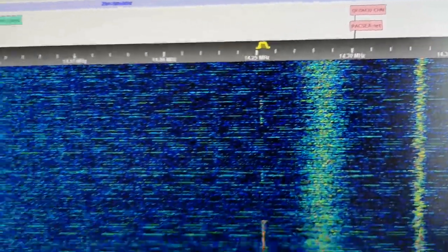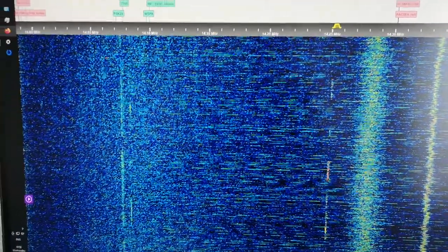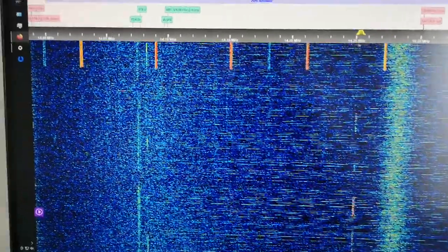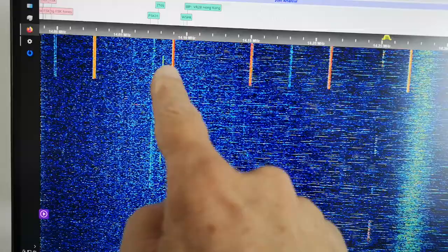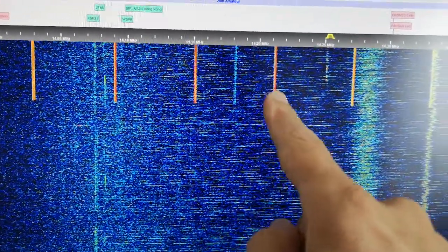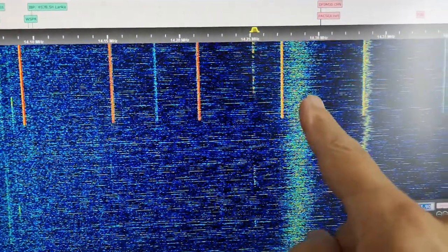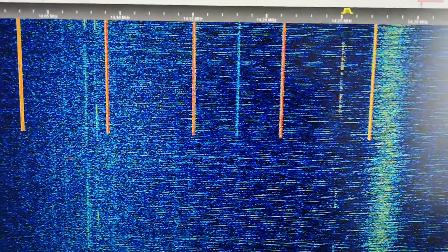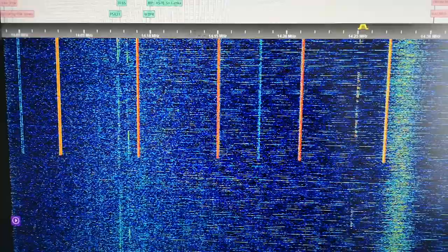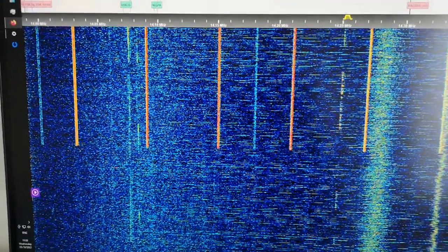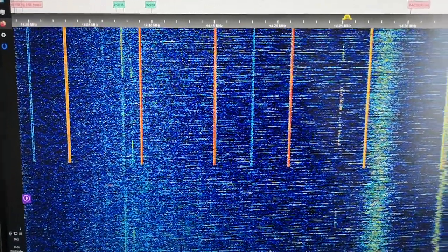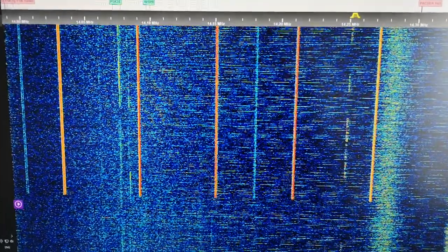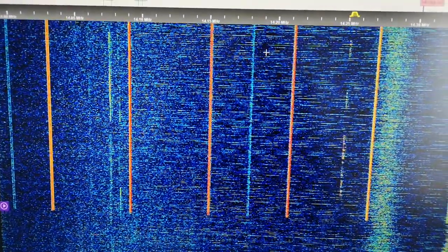It's now switched to 100, so the display's paused, but now it's reconnected at 100 megabits, and you can see here these red spurious signals. I don't want them there. They're about 30 kilohertz apart, regularly spaced over the whole radio spectrum, practically from 0 to 30 megahertz. They were causing a real problem. I could barely receive any other signals. And the simple way to make those go away was to change the speed of the Ethernet interface.